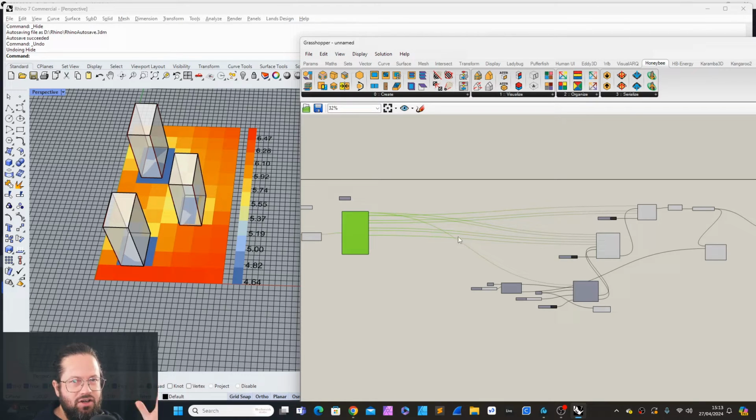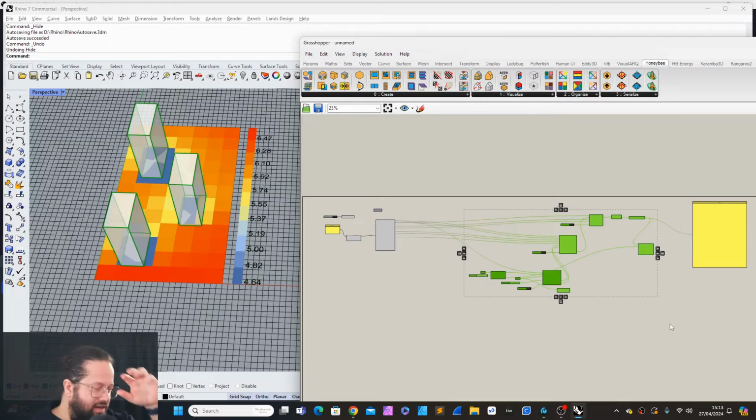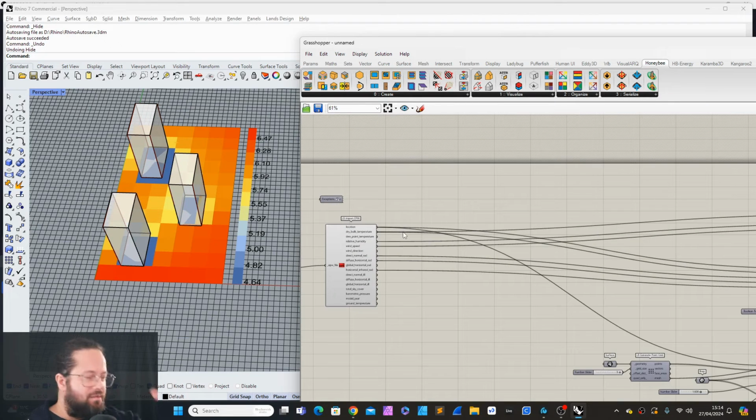And it's actually a good thing, because it will not calculate everything and then take a portion of the period. It will already be making the period smaller. We're working with a smaller set of data, which makes the calculation much faster. So instead of calculating a whole year, you could also calculate a half year, and that gives you a very good overview over the whole year.